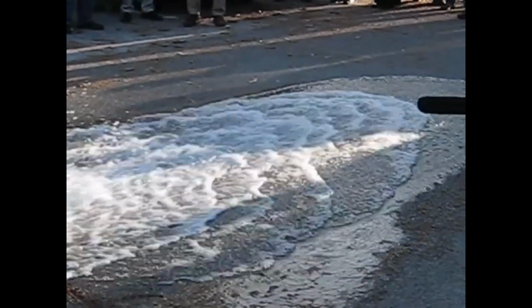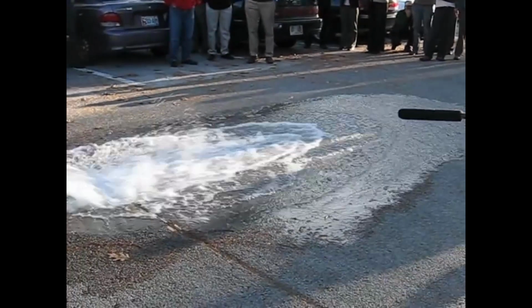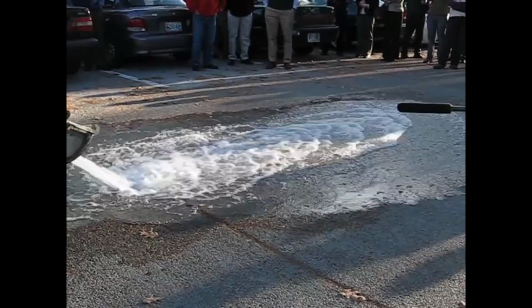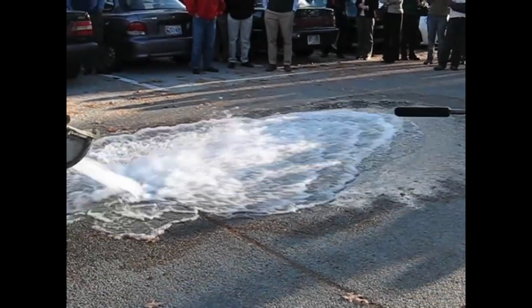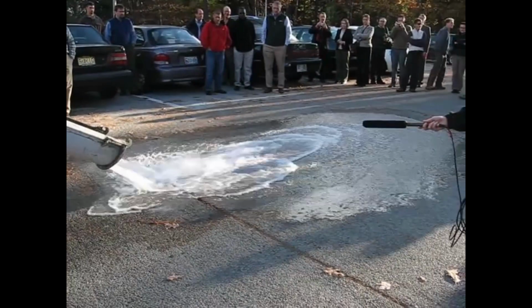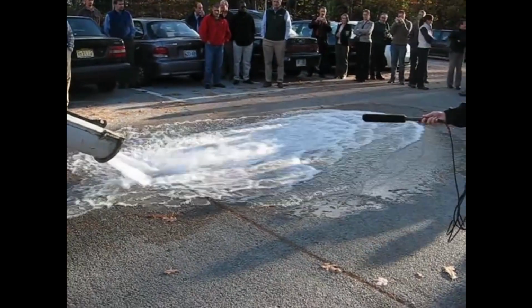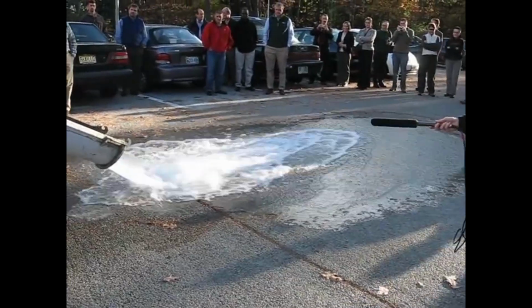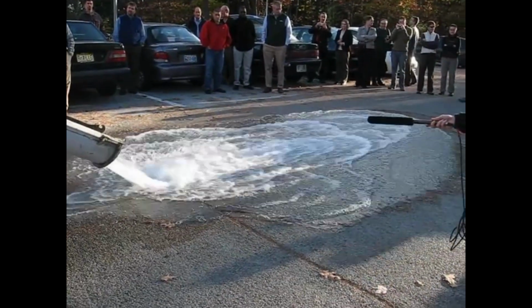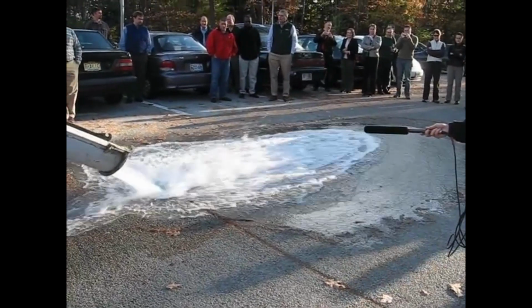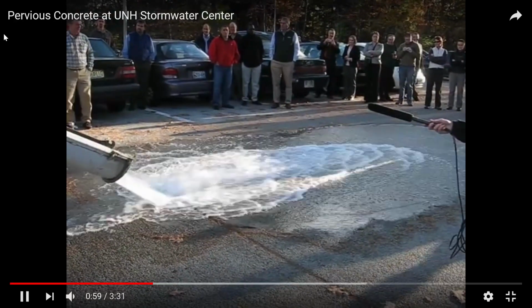So it's not a complicated recipe. The only challenge is in the areas that have the freeze-thaw cycle. If this porous concrete isn't well drained, then it's really vulnerable to damage, because if water is in there and it freezes, it's going to expand and then break apart the chunks of the pea gravel that are connected to each other. So it's really critical to have a good drainage system underneath porous concrete, and it looks like here they do.